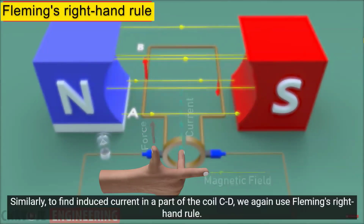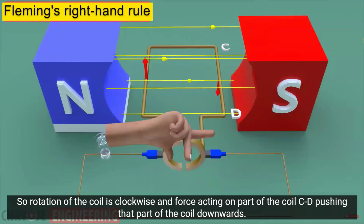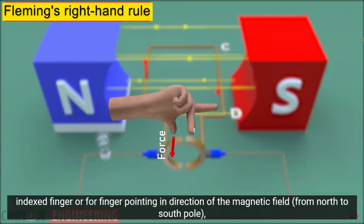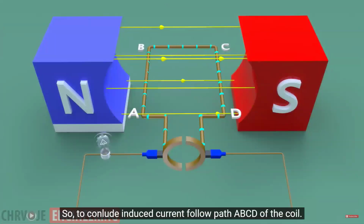Similarly, to find the induced current in part of the coil CD, we again use Fleming's right-hand rule. The rotation of the coil is clockwise, and the force acting on part of the coil CD is pushing that part of the coil downwards. The thumb points down, indicating the direction of the force, the index finger points in the direction of the magnetic field from north to south, and the middle finger will point in the direction of the induced current, which is in this case from C to D. So to conclude, the induced current follows the path ABCD of the coil.